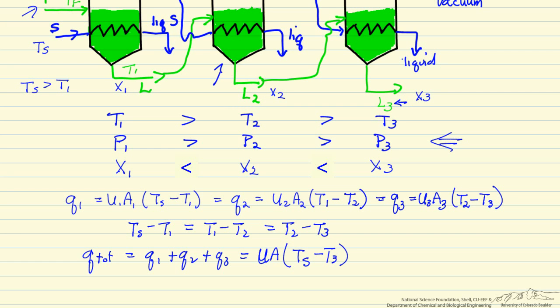To a first approximation, 1 kilogram of steam fed in here will vaporize 3 kilograms of our original liquid. A triple effect evaporator of this type is certainly best used if the feed is hot coming in, so we don't have to use much of our steam energy to heat the feed.